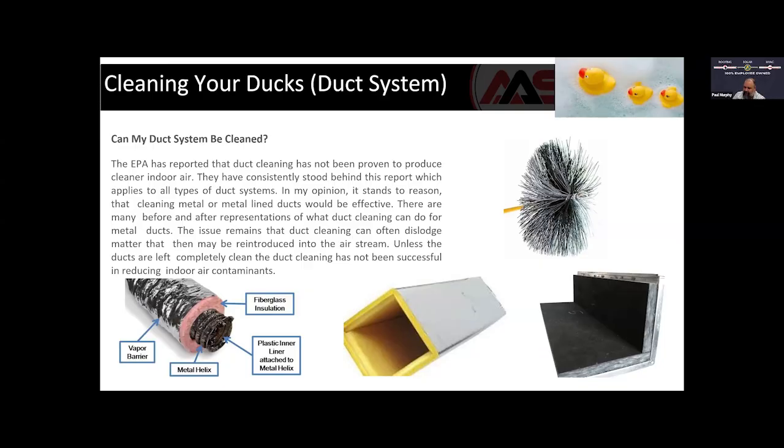And then you have metal duct that is called internal lined metal duct. And if it doesn't have a metal liner, then you just have exposed fiberglass. So we typically recommend that if you have that as well and you don't have a metal liner, that you don't get duct cleaning on it.